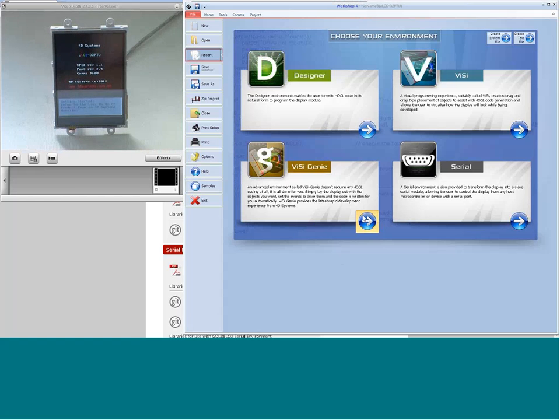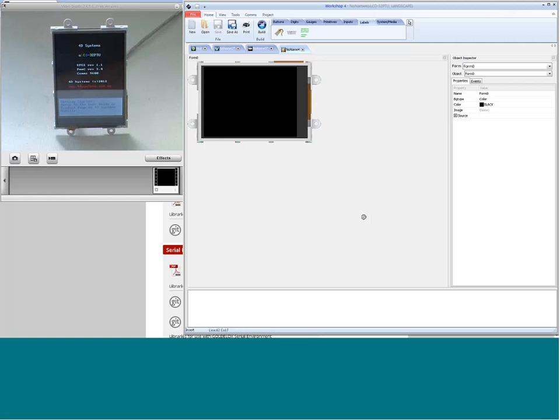So just a quick thing to add regarding this PLC question. You're not necessarily tied to using serial commands per se. You can create 4DGL code in the display and then send information via serial commands from a PLC or any host that triggers 4DGL programs on the module. And you can capture data and that type of stuff, and then display it in a graphical manner on the display. If you get what I mean.